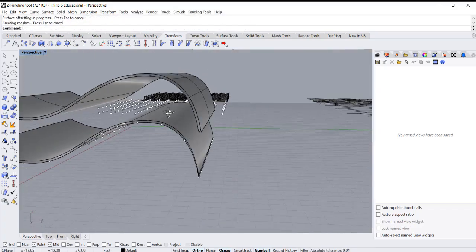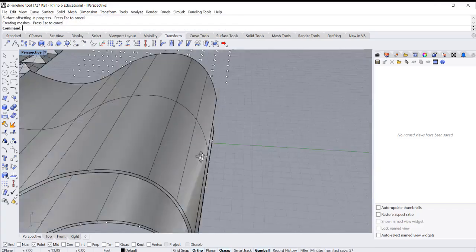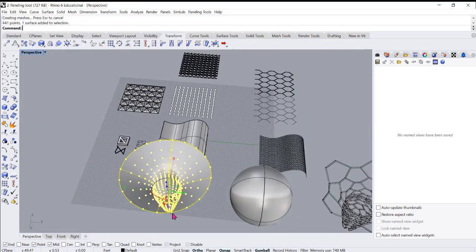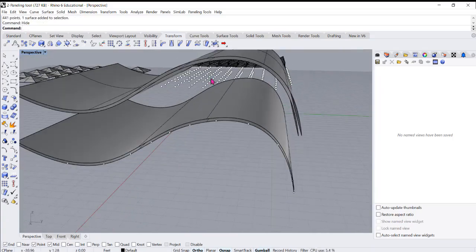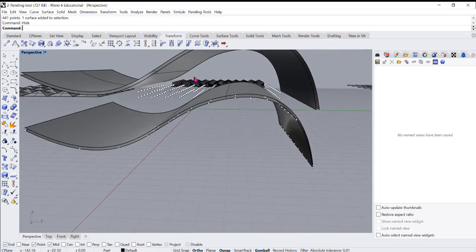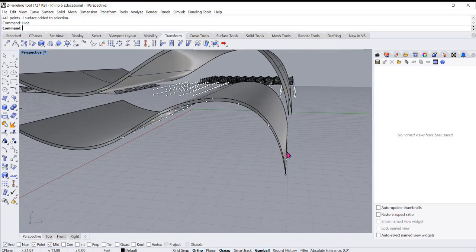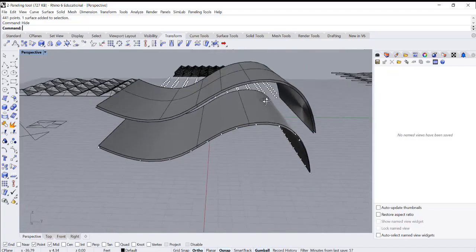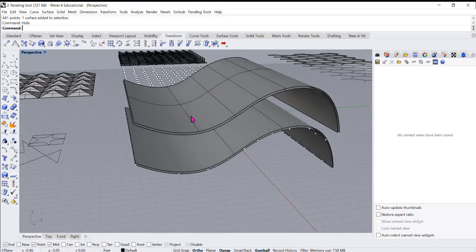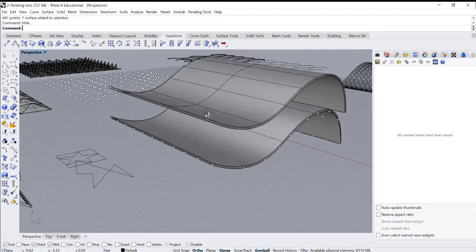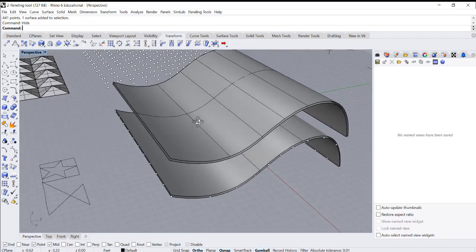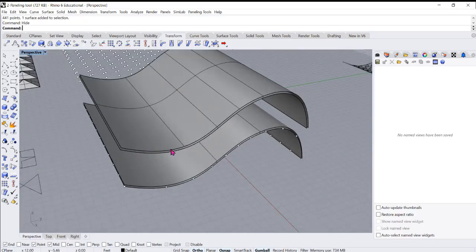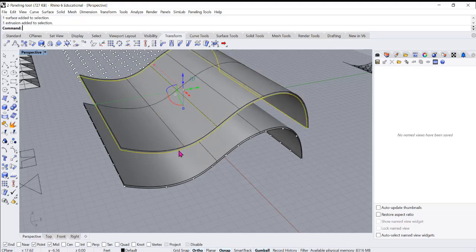See how now the offset surface, I'm going to hide this element right here because it's in my way, so hide. So you can see how offset surface now created the second surface, but it's not overlapping with the points right here on this area. So when you're creating a custom 3D on a non-regular or non-flat surface, you will need to offset the surface, and then you will have to create the points based on the bottom one, and then also based on the top one.